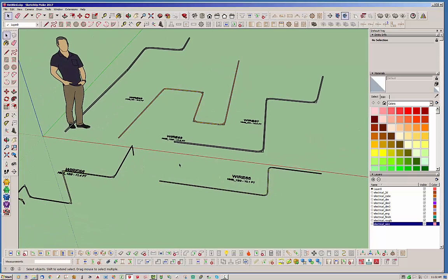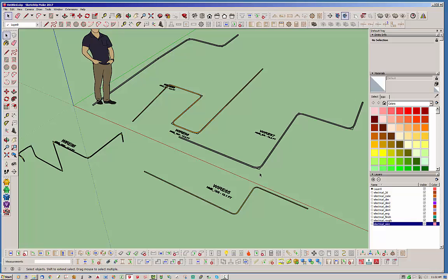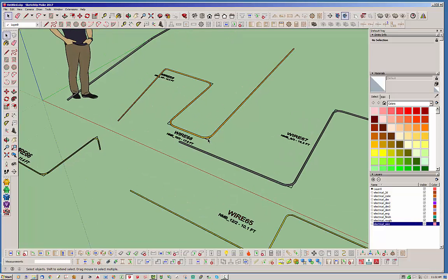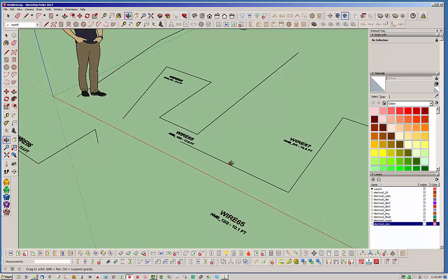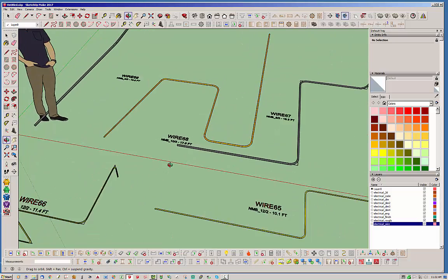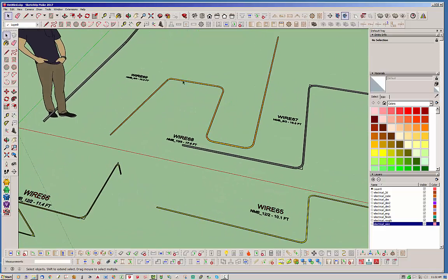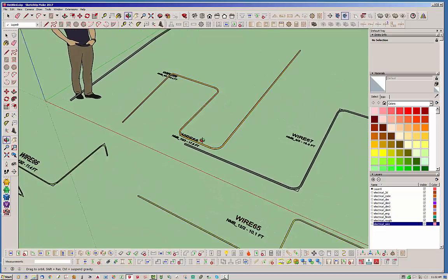I think that pretty much covers it. The only other thing I think that might be of a little bit of interest is, well, let's go ahead and, for instance, let's turn off that electrical wire layer for a second, and I'm going to take this little group of edges, go ahead and delete that, and then turn that back on. Now, if you right click on this guy, you can do what I call regening. So you can regen the wire assembly. And the reason why you might want this is maybe you've gone in here manually and messed something up and you just need it to redraw.